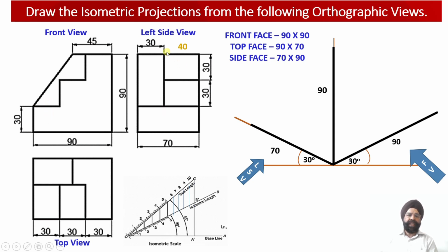So these 3 steps will have the width equal to 40 millimeter. So if we translate all these dimensions over there, we can check this is the width of the inclined web, right? So this is the inclined web that we are having. So in the side view, this inclined web will be shown over here. Okay, so this is the apparent shape of the web, which is inclined, and the inclination is observed from the front view as it is seen in the front view of the orthographic projection.